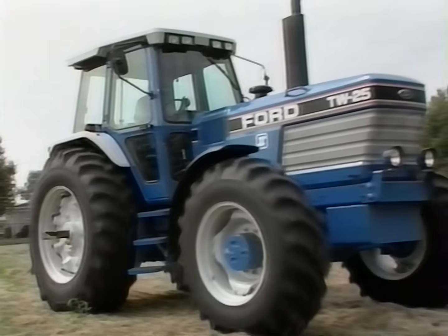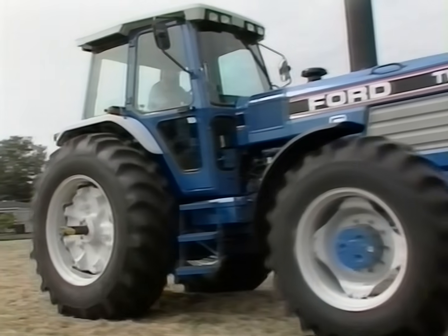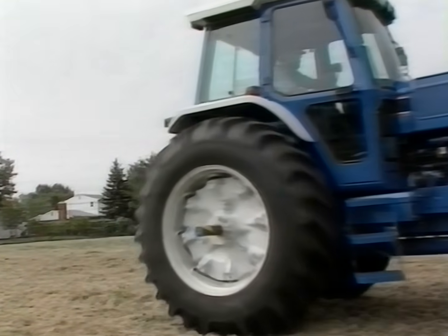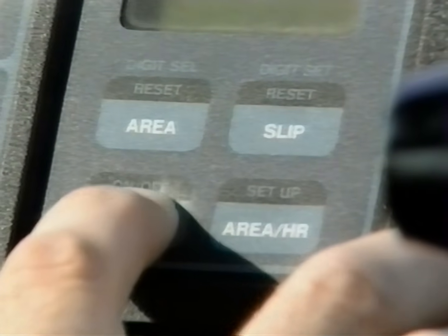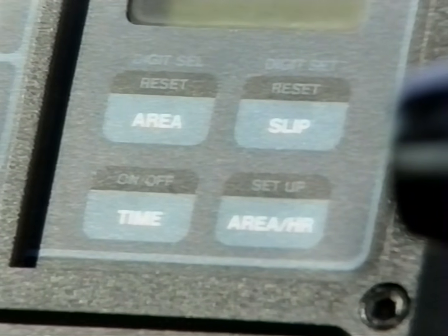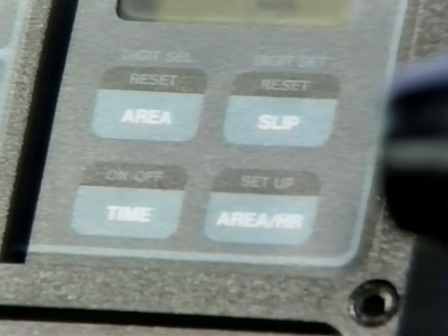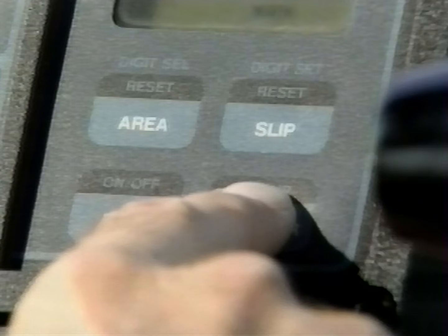Drive the course just as you did to obtain the calibration number. Use a slow, steady speed and press the on/off switch at the beginning and end of the course. At the end of the course, the performance monitor registers the distance it has calculated the tractor covered on the course. If this is within 4 feet of the 400-foot figure, the TPM is calibrated correctly and you can press down the setup switch for 3 seconds to return to the operation mode.